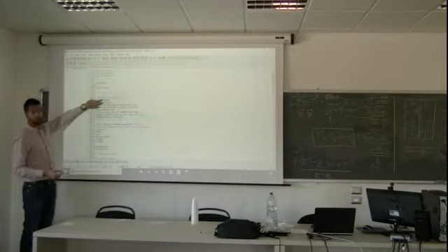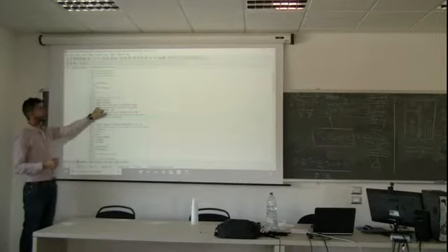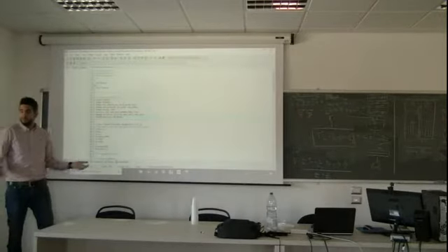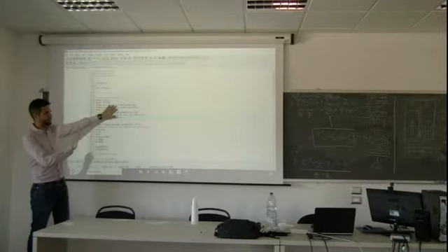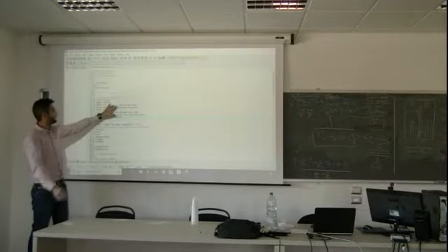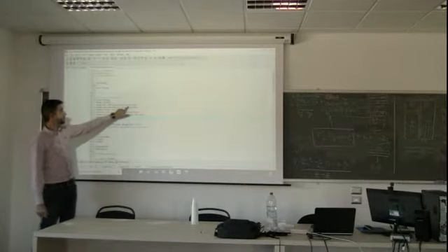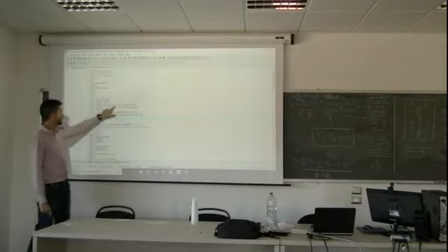Now, we understand this is the solution vector, this is the assumed vector. Now I need to define thermal conductivity as a float, because now it's 5, but thermal conductivity can be 5.5, for example. Density I don't need for this problem because it's not transient, but we will see it probably in the afternoon. Heat capacity the same. QB, I need to define QB. Heat transfer coefficient, I need to define as a float.